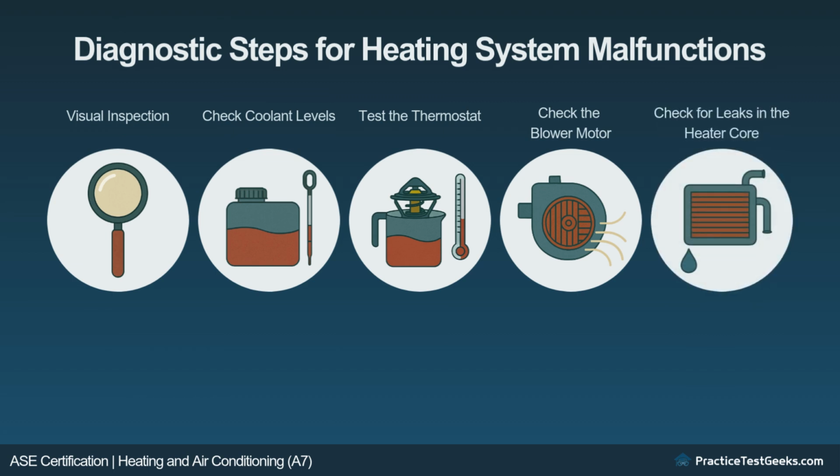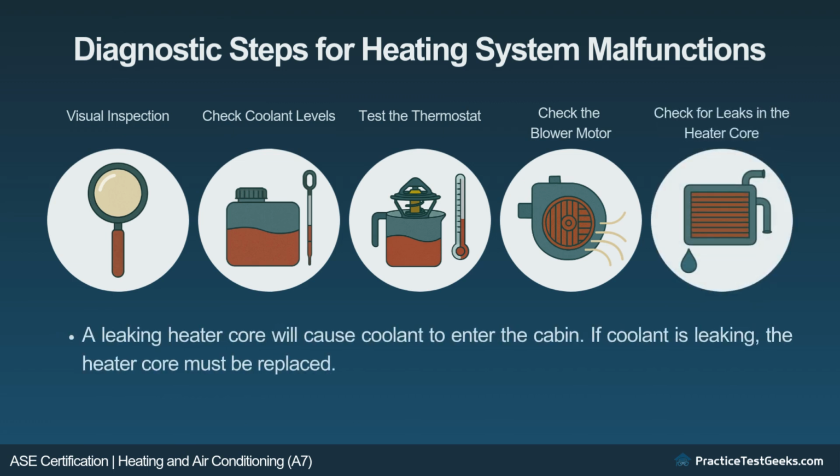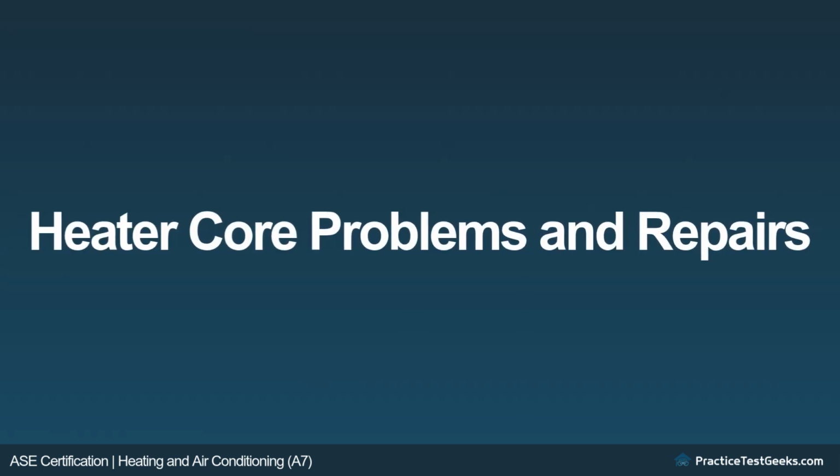Check for leaks in the heater core. A leaking heater core will cause coolant to enter the cabin. If coolant is leaking, the heater core must be replaced. Heater core problems and repairs. The heater core is a crucial component in the vehicle's heating system. It works by transferring heat from the engine coolant to the cabin air.